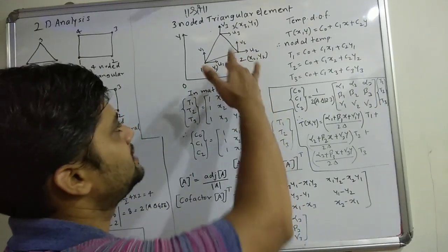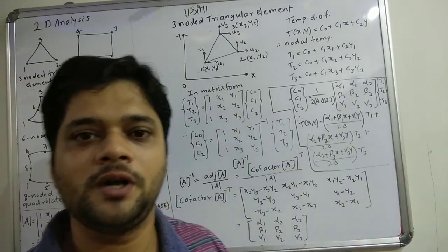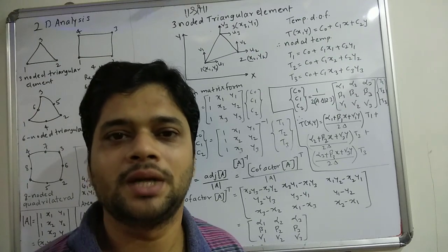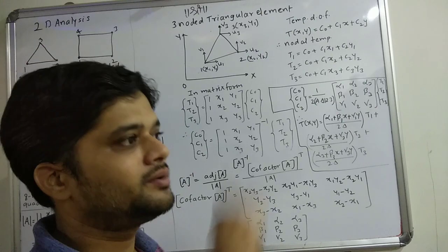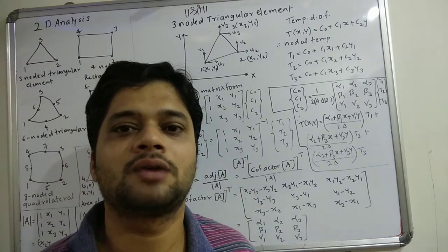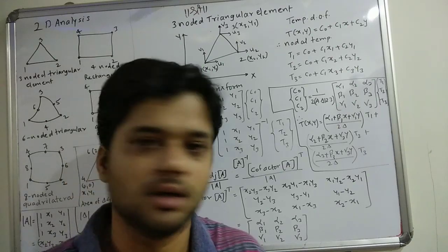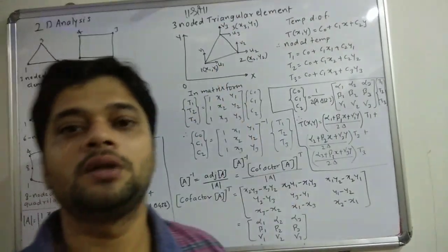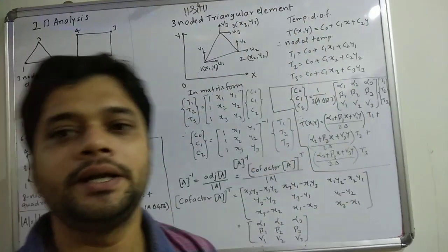So if we apply this concept on a thermal field problem, then on each node I will only have 1 degree of freedom, that is temperature, because temperature doesn't depend on x direction or y direction. Temperature being a scalar quantity, it spreads uniformly, so it doesn't have a direction specificness. That property of thermal field we will use, and the degree of freedom gets reduced to 1.